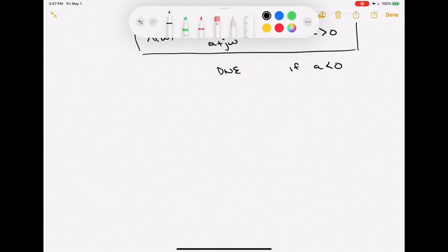We're going to do one more and then we'll be done with this particular lecture. In this next one, I'm going to do probably the easiest transform you can dream up. So this is example 2, and I'm going to pick a signal that is just a little bit weird. This is our hammer function that we use to whack systems to try to figure out what their behavior is, right? So if you think about applications of this Dirac delta function, what did we do? We took a linear time invariant system, we hit it with a delta function, and out came h of t.